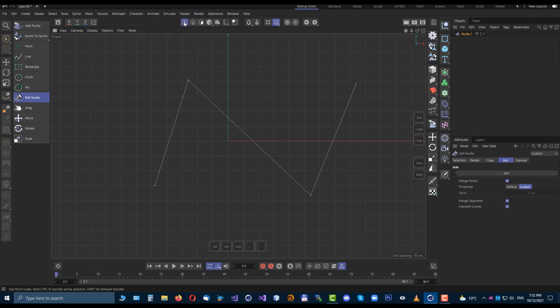And finally, in point mode, you can select in which points exactly you want to disconnect or connect the geometry. So let's say this curve, I want to disconnect this curve and explode. It is now exploded into 2 points, and in element mode you can select 2 separated curves. If you want to connect this back, you have to select now. You can see now you are selecting 2 points. So if you select these 2 points and use join on these 2 points, the neighbor geometry is connected together. So now in our case it is back to one single 3-segment polyline.